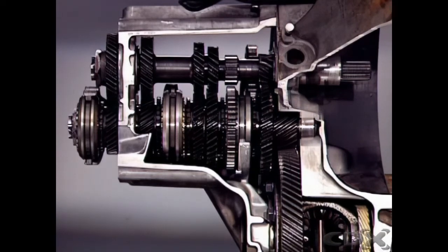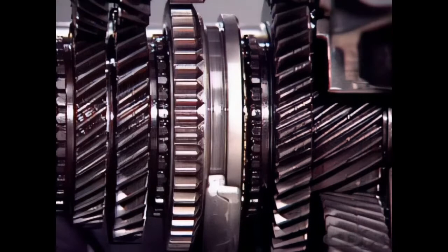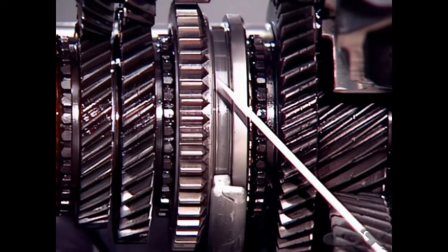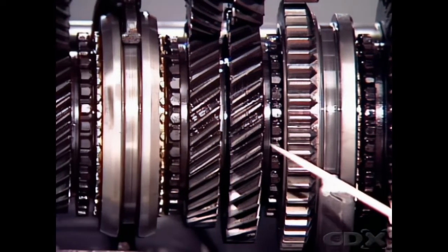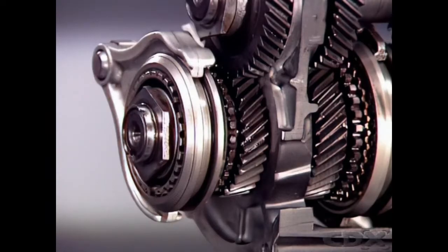In transaxles, the synchromesh unit plays a similar role. It is located between the end of each engagement sleeve and the gear. In this layout, the engagement hub and sleeve for first and second gears is on the secondary shaft, as is the third and fourth speed hub. The fifth gear engagement hub is at the end of the secondary shaft, furthest from the main drive pinion.